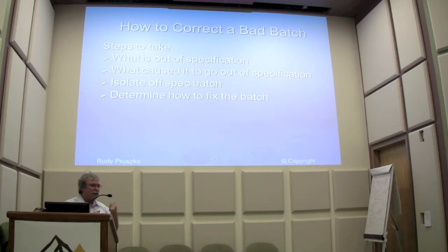I had a plant that was running in Kentucky that called me up and says, hey, we're getting a whole bunch of soap being made. I said, well, what feedstock are you using? He says, well, we were using degummed soybean oil, but we just switched to vegetable oil. I said, how much moisture is in your vegetable oil? Oh, well, it's got quite a bit of water in it. I said, okay, what about free fatty acid?